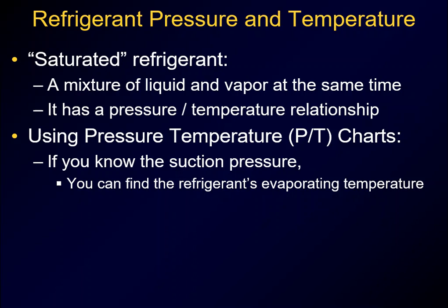So, one of the things that you'll hear me say a lot: all of this is about temperature. It's about heat. A lot of people get caught up in wondering what their pressures should be on a certain system. And so the first thing they look at is PSI. They go to their gauges and they say, well, how many pounds should I have on suction, or how many pounds should I have on head, on this system? Well, the first thing I'm going to ask is, what are your temperatures?